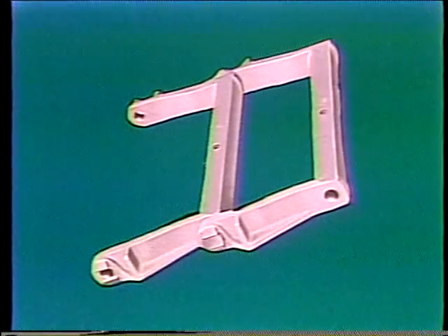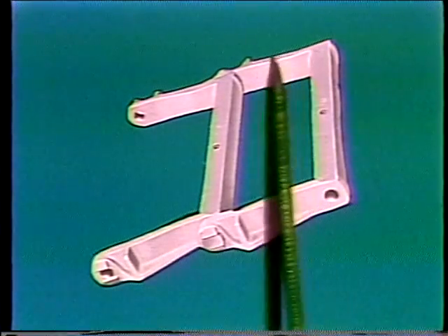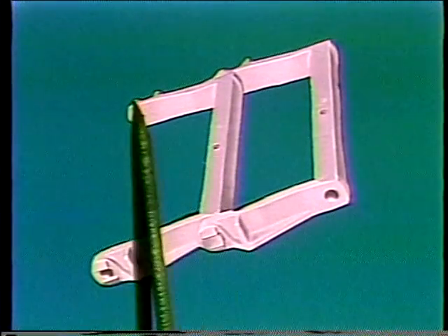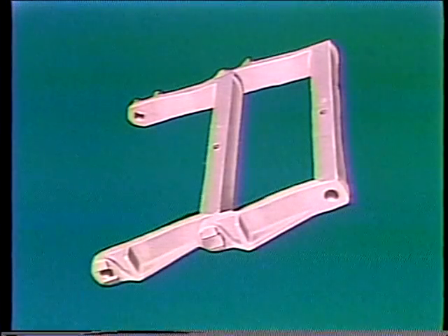There are also various types of drag chain conveyors which use the chain itself as the medium for the material handling. There are various types of cable conveyors where wire rope is used, an application similar to overhead type conveyors, except here the wire rope is used instead of chain. There are systems which use chain that's installed in grooves in the floor, which in turn pull wheeled carts.